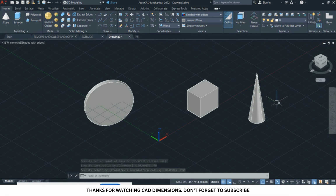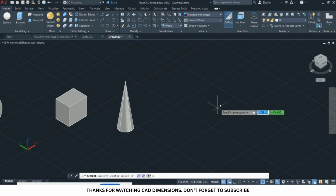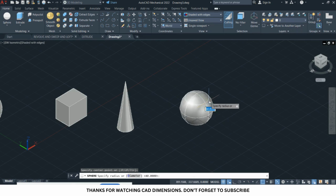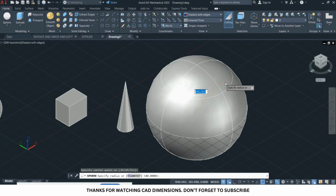Let's look at the next one. Let me use the view cube or the navigation here to be able to pan, and let's look at the next one. So the next one is a sphere, which is also another solid primitive tool. Once you specify the first point, you can also specify the diameter of your sphere, or the dimension you want to give to it.